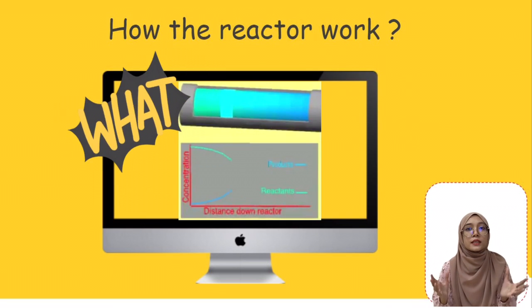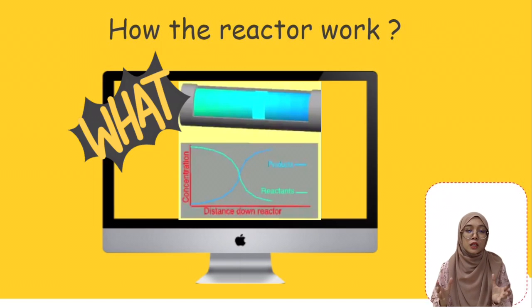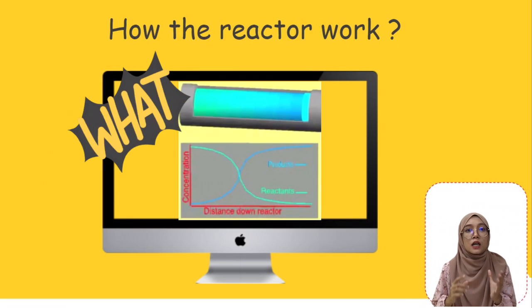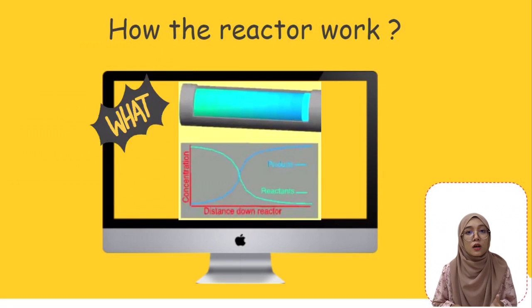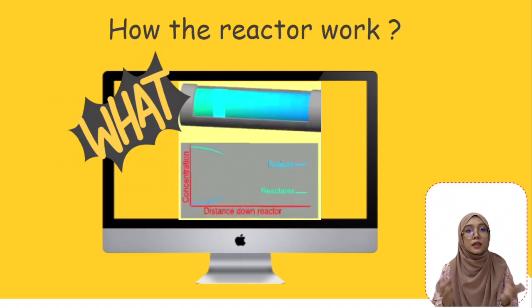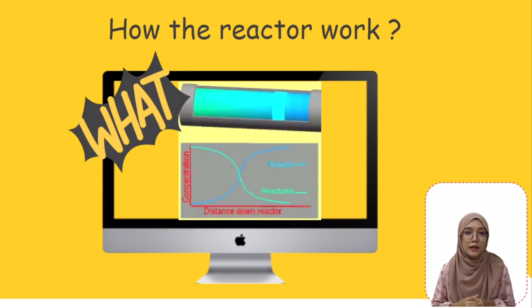A plug flow reactor might be configured as one long tube or shorter tubes, which range in diameter based on construction cost, pumping cost, the desired residence time, and heat transfer needed. Usually, short diameter tubes are used with high reaction rate, and vice versa.